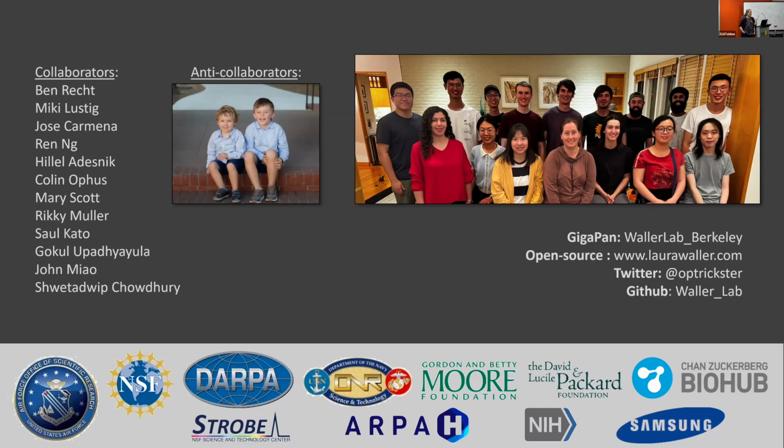Just a different regime, but it's similar. They're both just PSF engineering. Right. You could design a phase mask that sits fairly close to the sensor. If it has lots of high frequency information, you can move light to high angles and get a smaller PSF, which is like piling the light together more.